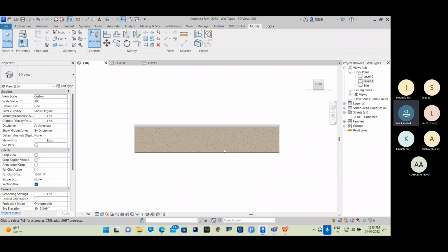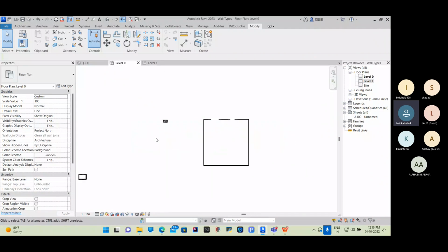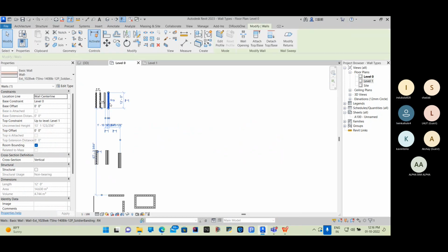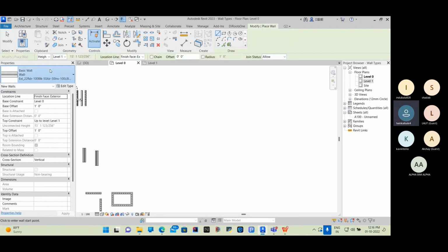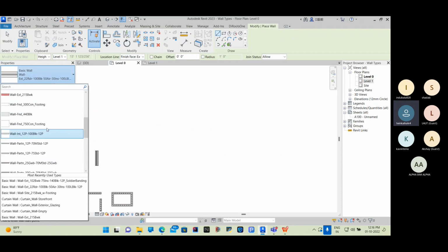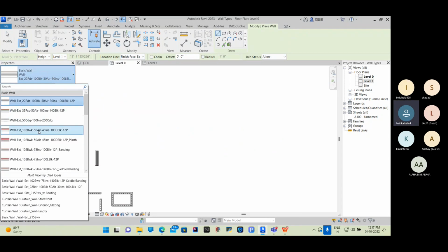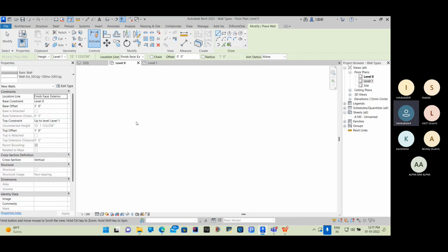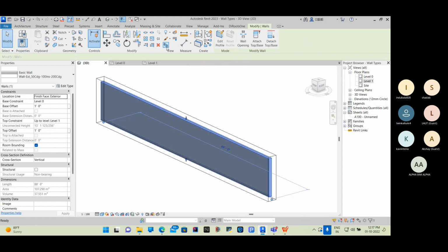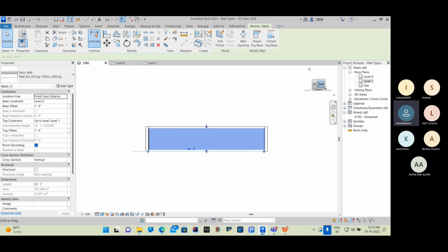So this is how we create openings and control the wall. Now, I'll create a new wall. No problem, any new wall. For example, select a wall. We don't have any generic wall having a single layer, so I'll just use pick any wall. Okay. So I just created this wall, and this is the section box. If we select any element and press BX, we get to see that element only.